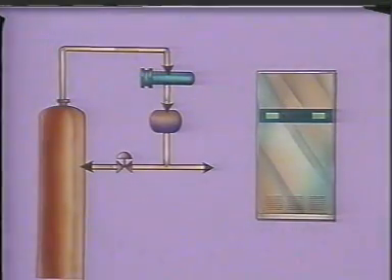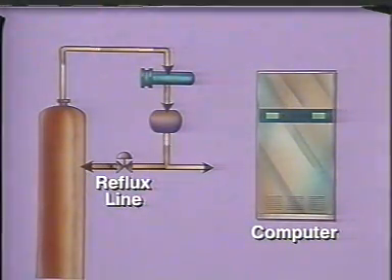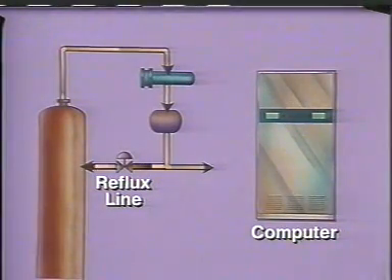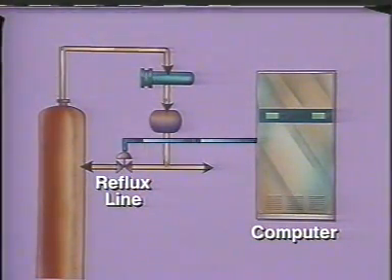If there is a change in the condition of a process variable, like reflux temperature, the computer immediately calculates how this change will affect product composition. The computer can then adjust the tower operation to keep the column producing on-specification products at the lowest possible cost.